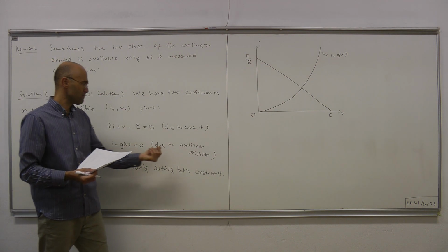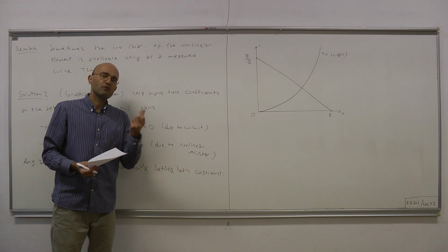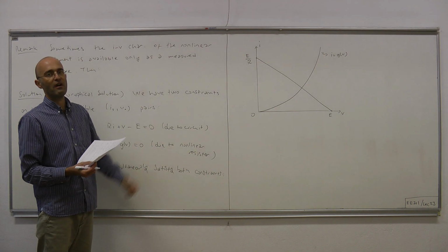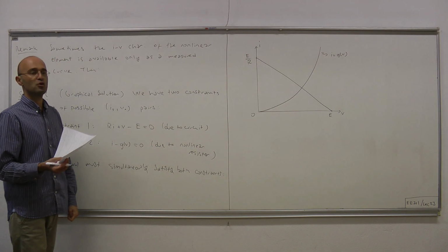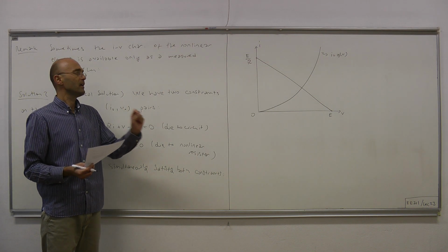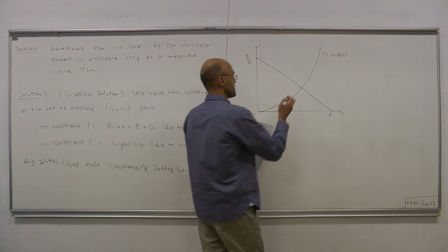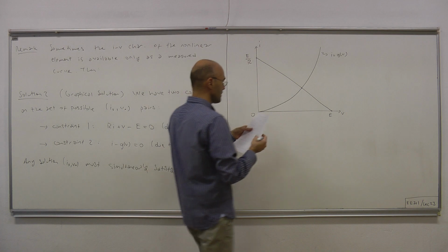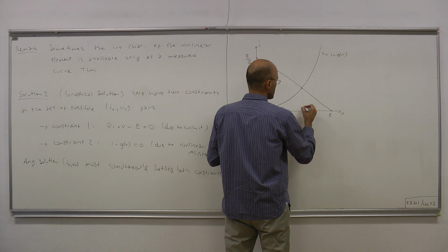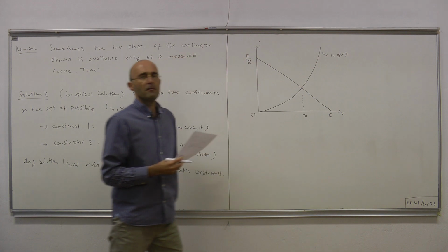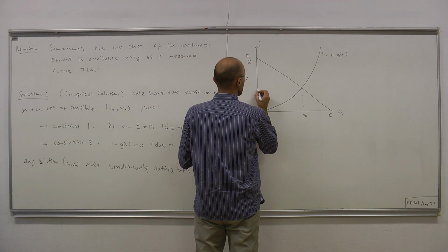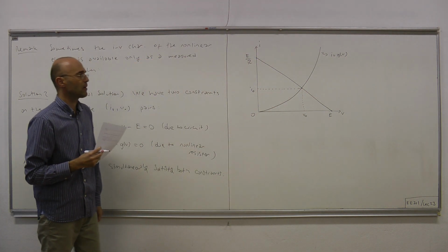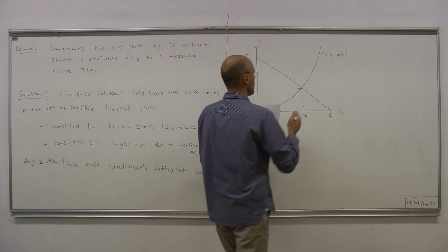Since in a running circuit the current-voltage pair for the nonlinear resistor should satisfy both of those constraints, clearly, from the graphical point of view, the operating point or the solution is where those two curves intersect. In our picture, it corresponds to this point. So the voltage of this point is the operating voltage, and the current corresponding to this intersection, I0, is the operating current. And this is called the operating point.